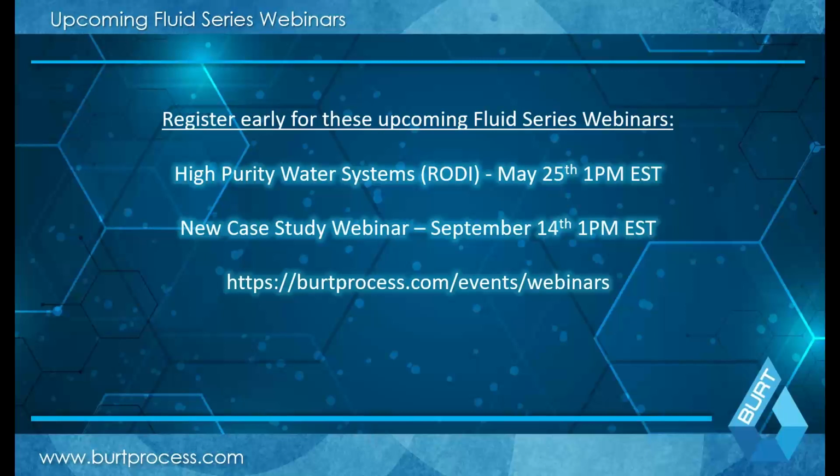So that's what I was saying before. We do have systems which utilize pH neutralization. Again, cyanide destruction, I don't see it too often anymore, as it used to be much more common, say 20 years ago. A lot of the cyanide has kind of gone overseas at this point, but we still do it. Same thing with HF reduction, and even some chemical biokill systems, kind of a similar thing. They utilize another chemical in addition, and they utilize pH as part of that overall system.